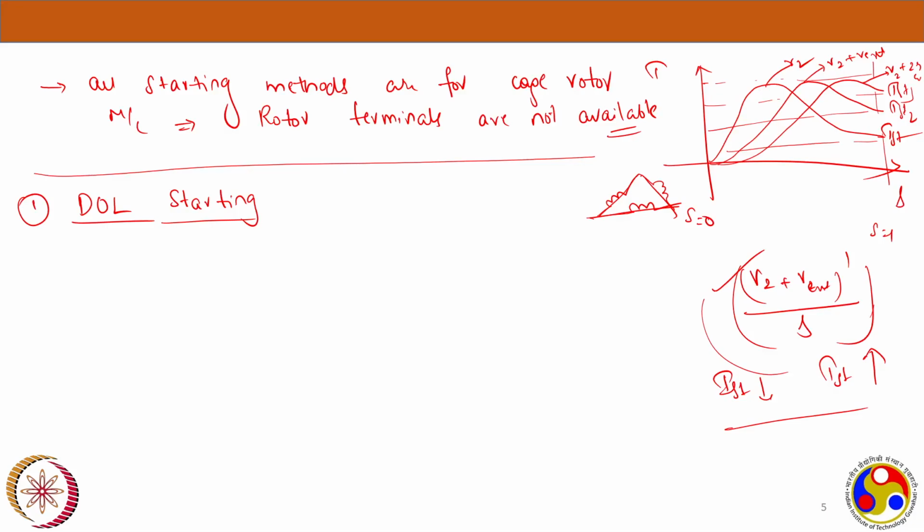That's why I'm taking the stator as delta, because for the star delta starting, the stator needs to be delta. That's the mandatory thing for it. So to have the same convention for all the methods, I'm assuming the stator for the starting methods to be a delta one. Okay. Because star delta is only possible if your machine is delta connected. That's why. Okay. Now, direct online starting.